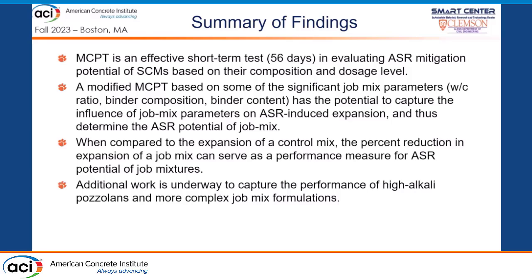So I don't want everybody here to go berserk over the alkali release from these SCMs. Usually that is not the case, but you should be familiar with it. There are certain SCMs that do contribute that. But we're looking at implementing that as well in the MCPT, looking at how to model the pore solution compositions in those systems so we can match with the soak solution and apply it to the job mixture.